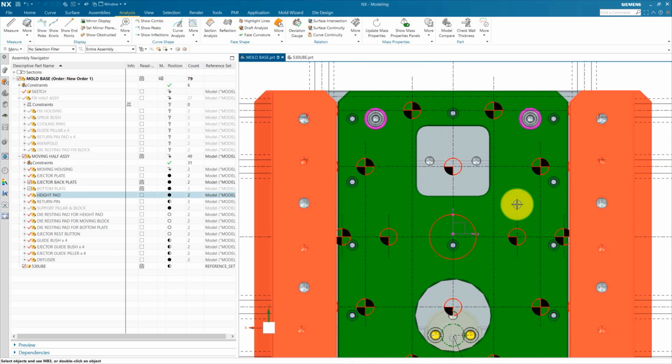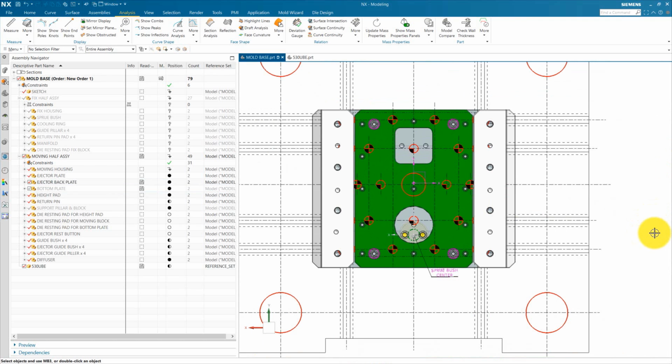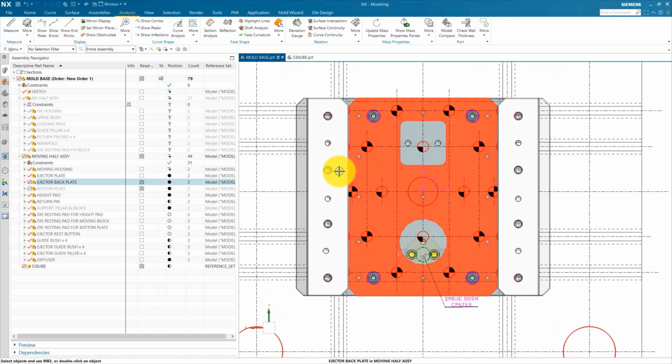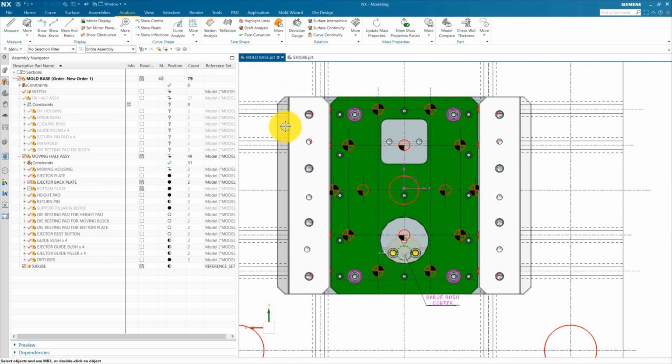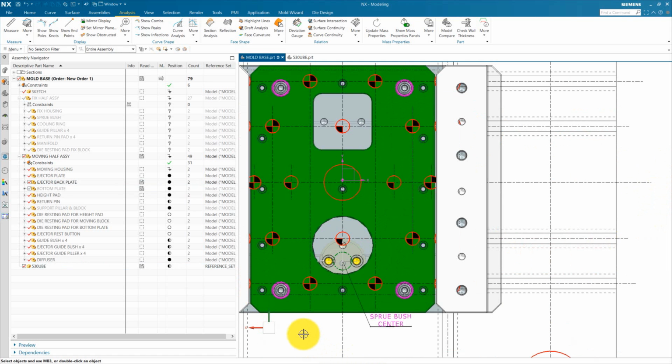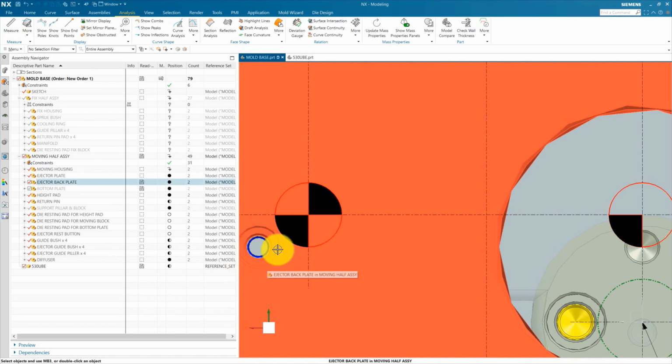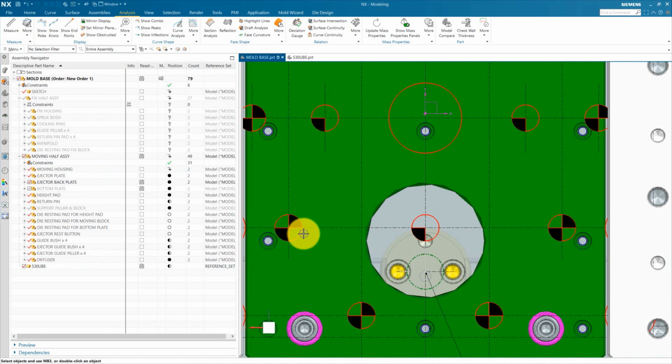We need to add an ejector bumper hole inside our ejector backplate, which is a threaded hole. So the ejector bumper rod is connected to our ejector backplate, and it is used to eject the ejector assembly and reverse the ejector assembly. So we need to choose 4 holes which can balance our ejector assembly. So we are going to choose these 4: 1, 2, 3, 4. We need to check also whether the bolting hole and ejector pin hole are available or not. We can move the bolting hole a little bit, but this is okay. This does not go to our threaded hole.